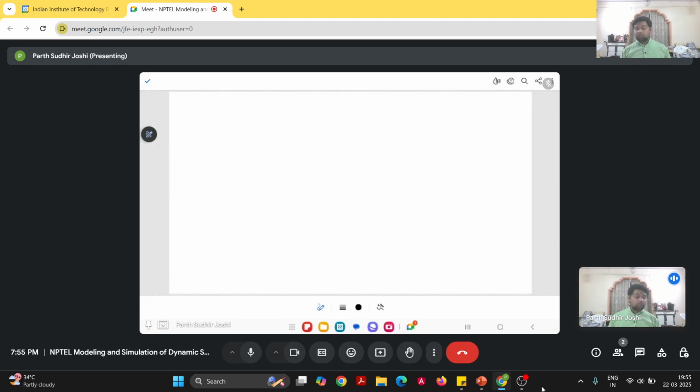Now further, if we want to draw the bond graph for this system, what we get is that the source of effort is the input torque T in. Part of the mechanical energy is being consumed in rotating the mass, or the inertia of the pinion. So we can write it as a one junction. And some part of the energy is also being lost in the bearing friction.